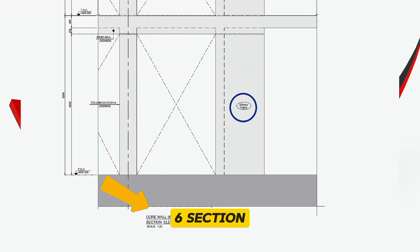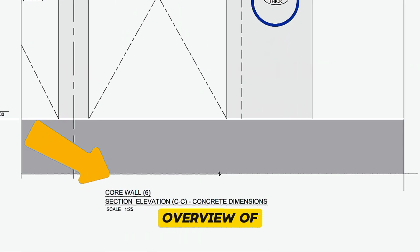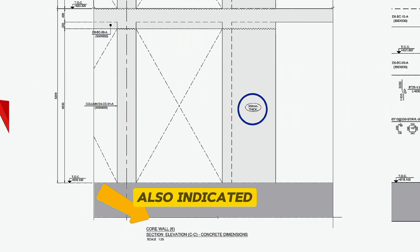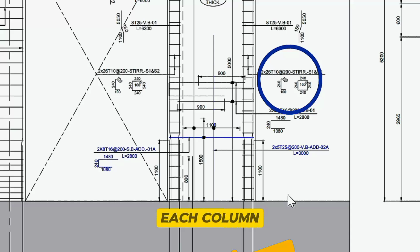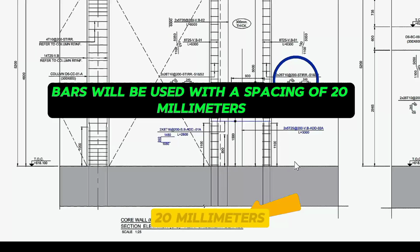Core wall 6, section elevation CC, shows concrete dimensions and an overview of section C, where the wall thickness is 300mm and the construction joint line is also indicated. The elevation CC reinforcement details show the lengths of vertical steel bars in the columns. In each column, 1 stirrup and 2 link bars will be used with a spacing of 20mm.